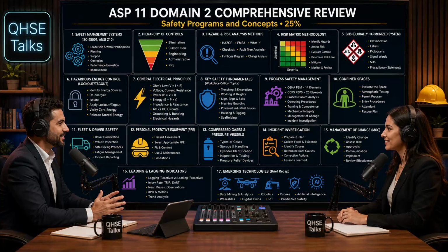If even a tiny fraction of a milliampere goes missing, meaning it has found a ground path through a human body or water, the GFCI detects that imbalance and severs the circuit in a fraction of a second, long before the current can induce ventricular fibrillation in the heart. That is a brilliant piece of engineering. We are essentially measuring the math of the current to save a life.